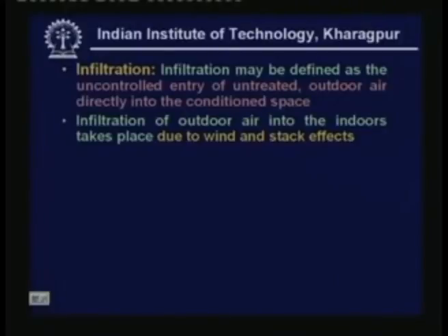As the name implies, the wind effect means infiltration due to the wind blowing over the building. Whenever wind blows over the building, pressure differences are created. Because of these pressure differences, outside air enters the building and air from the building leaves the building. This is what is known as the wind effect, and the second effect is what is known as the stack effect.